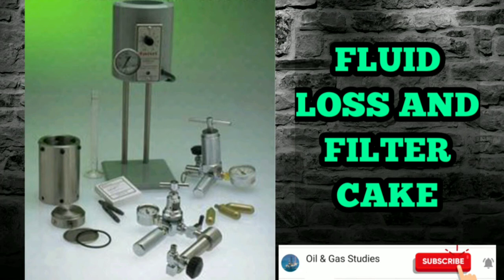Apparatus: both tests work on filling a cell with drilling fluid, and sealing it shut. Inside the cell is a filter paper that has been placed between the mud and the aperture in the cell. Pressure is applied to the cell, which forces the mud and solids through the filter paper. The solids accumulating on the filter paper form a filter cake, and the filtrate passing through the paper is collected in a graduated cylinder. The mud in the cell is pressurized for 30 minutes and the fluid or filtrate is collected and measured. The filter paper is also collected, washed, then examined, and the deposited filter cake is measured.